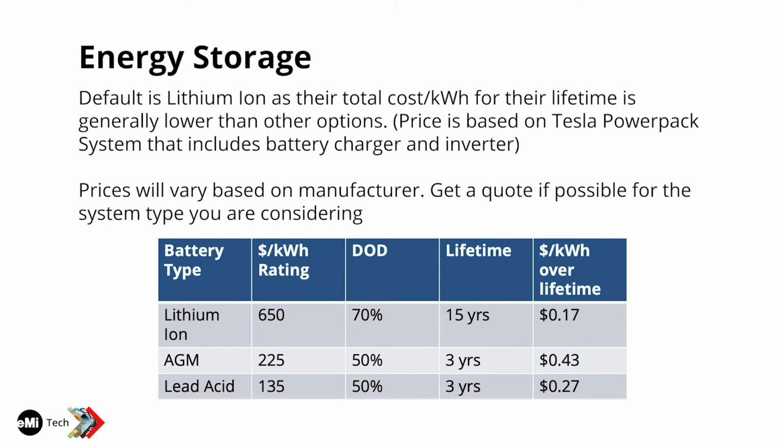and then you have to look at the depth of discharge. How much can I actually discharge the battery? And the battery industry is interesting in that you'd think that if you could only discharge at 50%, this rating would be the 50%, but it's not. They give you the full rating of the entire battery and then tell you you can't actually discharge that full amount. So you have to look at the depth of discharge, and then that depth of discharge will affect the